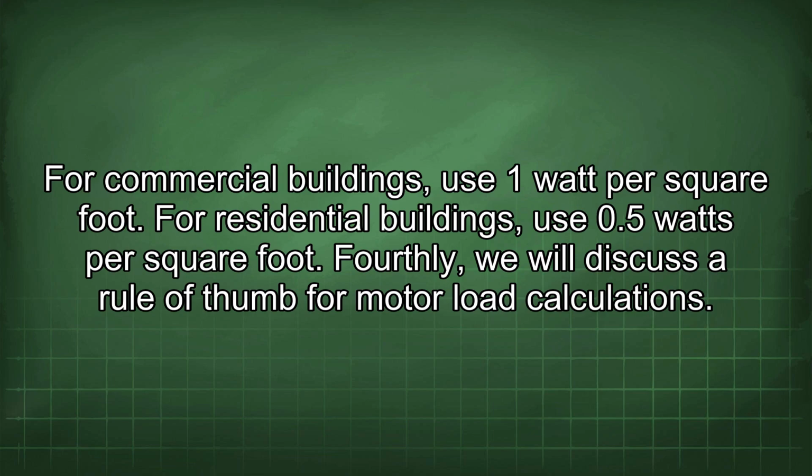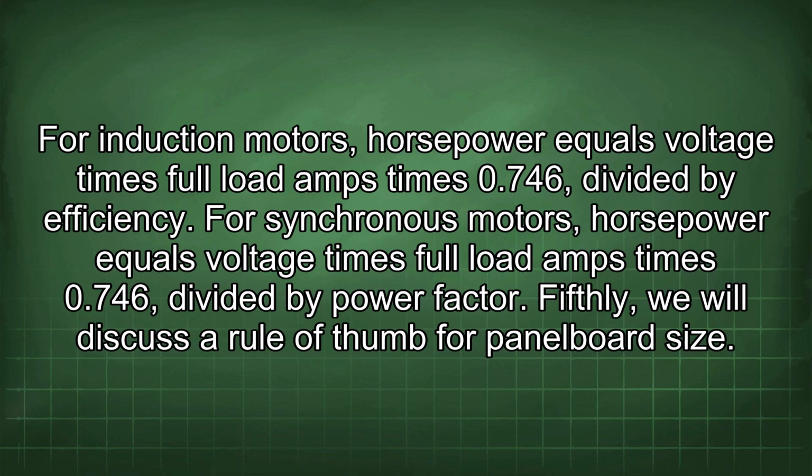Fourthly, we will discuss a rule of thumb for motor load calculations. For induction motors, horsepower equals voltage times full load amps times 0.746 divided by efficiency. For synchronous motors, horsepower equals voltage times full load amps times 0.746 divided by power factor.